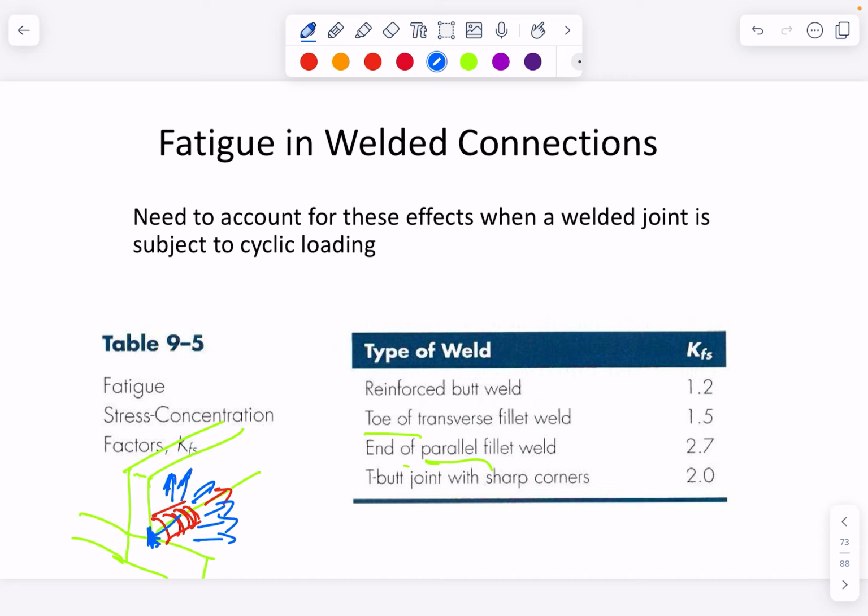And so this first little bit of weld here is probably not going to be as good as a little bit into it. Same time, by the time I get down to this other end, I run out of metal on the parent metal to absorb the heat, so it may overheat a little bit, but it's also where I stop the arc, and so I may get a little bit of less fill in my weld. So I might have a cold start, and I might have an underfilled end. So we've got stress concentrations, basically, at the ends of the welds.